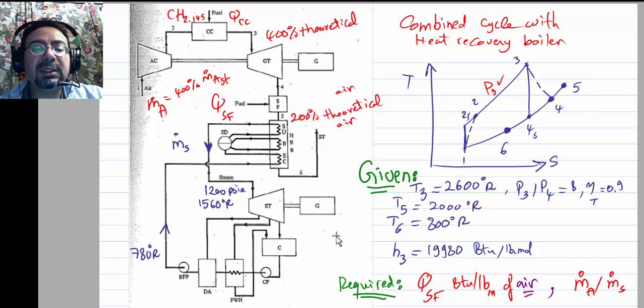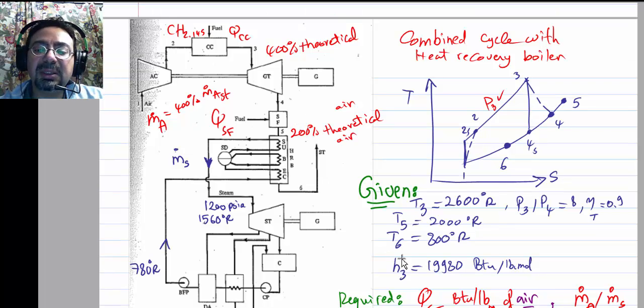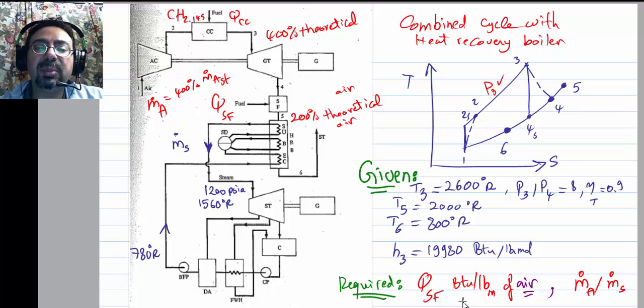So it looks complicated, but he's actually asking for a very simple thing. He's asking how much Q he needs to send over here, the Q that we are sending in BTU per pound of air. That part is complicated, per pound of air, because what's coming in here now is not just air, it's air with fuel. If you neglect the fuel part, the problem becomes much easier. But if we want to do a good job, then we have to convert from the exhaust mass flow rate to just pure air, because he wanted the calculation in BTU per pound of air.